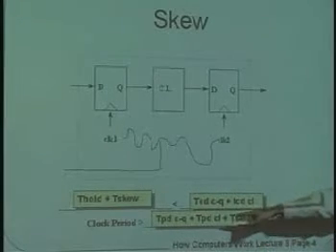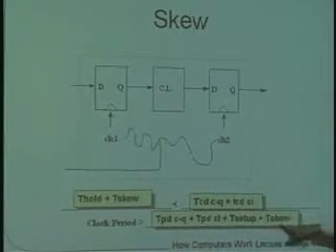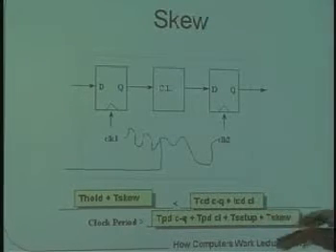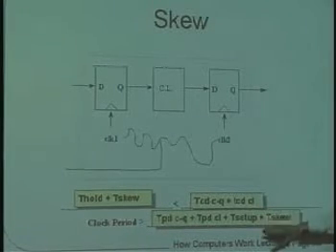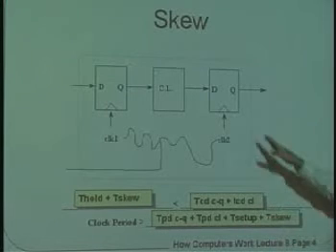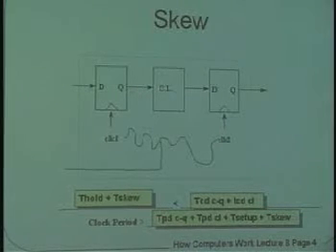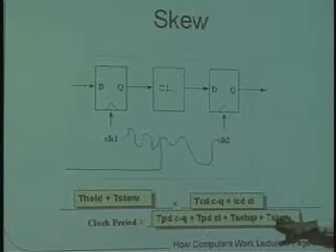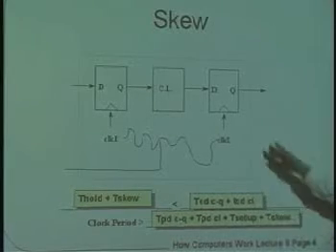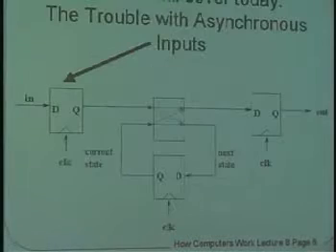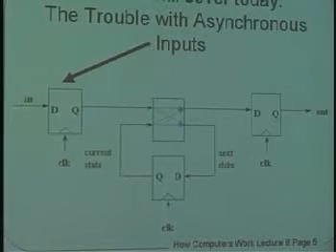The clock period needs to be a little bit greater than it used to be because we have to take into account the skew. And this is a measure of the absolute sort of worst case difference. This is always going to be a positive number between different clocks in the system. And so if you have a nanosecond or something like that, you would put that in here to indicate the amount of clock skew that was in the system. But anyway, that's all by way of review.